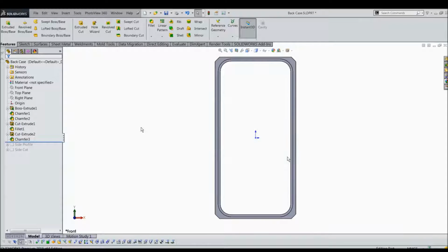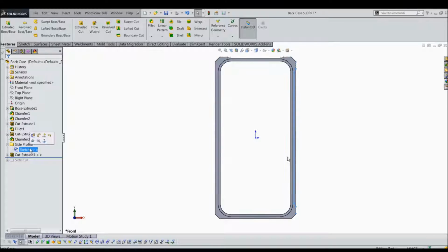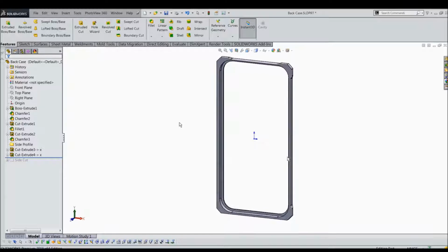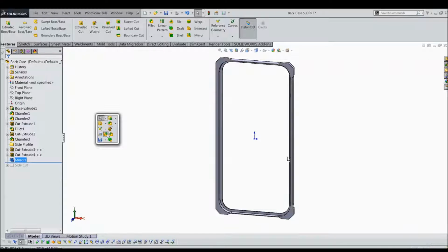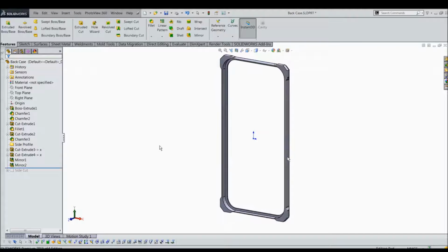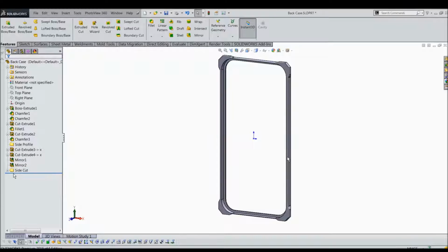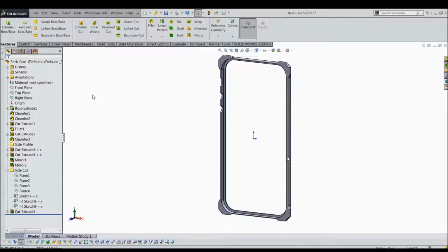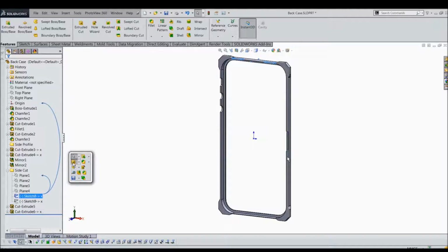Another great thing in SOLIDWORKS is that it allows us to easily reuse the sketches from previous design. For example, the profiles of the cutting features on the boundary. We could save them and insert them beforehand. And then, when the model is done, we just need to cut out those sketches and create an extra cut from there. You will notice that the cutting profile is not necessary to be a close profile. This flexibility in SOLIDWORKS does save us plenty of valuable design time. We could also apply the same method to create the cutting holes for the buttons on the side as well.